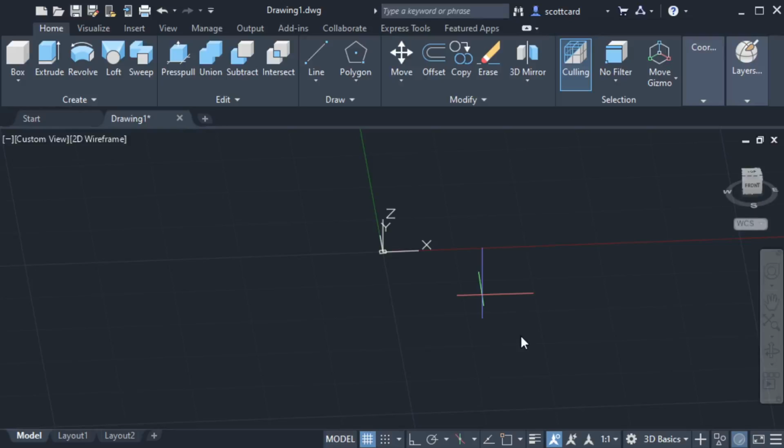What circumscribed means is that if we drew a circle around the outside, it would basically be touching the points of your hexagon. And so because the dimension they give us is 26 millimeters across the flats, we actually want it inscribed. All right. And notice that it is asking for a radius, so we're going to have to be careful of that. And so what I'm going to do is say that this is 26 millimeters divided by 25.4, because my drawing is in imperial right now.